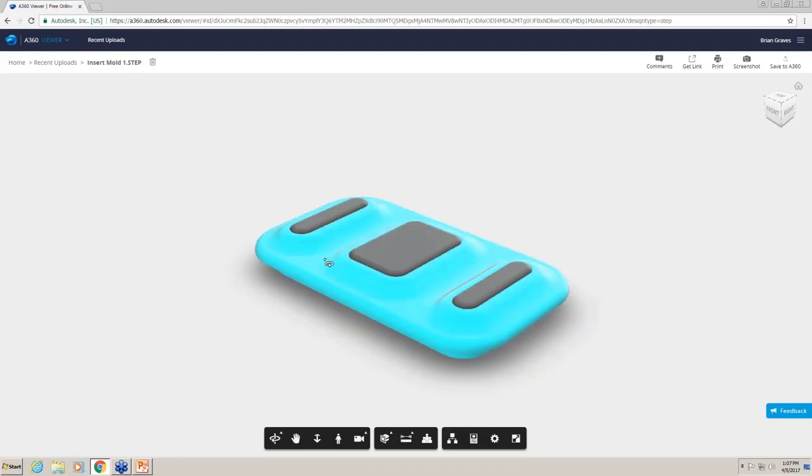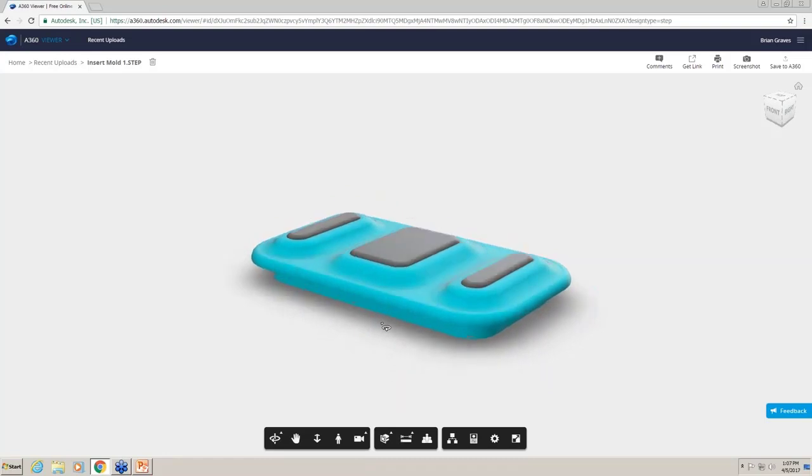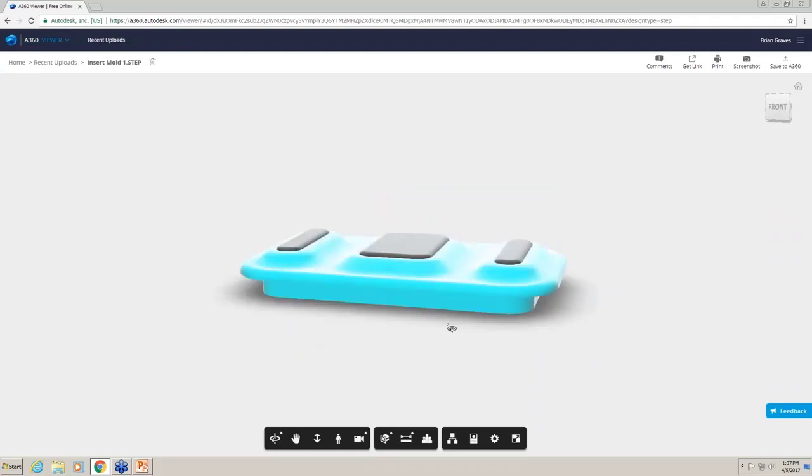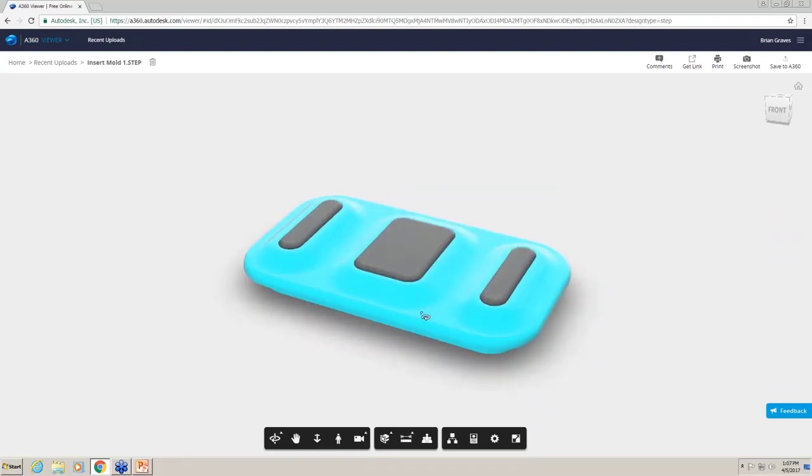This is the metal, and this bluish portion here, that's the actual molded resin. Now, one thing to take away from this is you see these inserts. There's not much surface area. There's not a lot to grab onto. Typically, this type of insert molding would need to be done in most likely a vertical press. That's something that's challenging. Not a lot of molders out there have something like that.